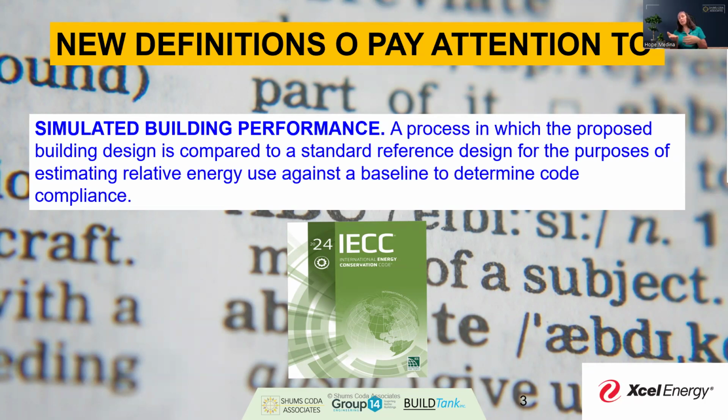As you can see on the screen, it's a process in which the proposed building design is compared to a standard reference design in determining the estimated relative energy use against what a baseline would be. And that is going to determine whether it's compliant with this particular compliance pathway.